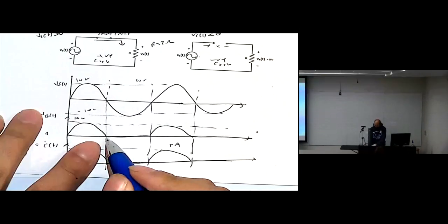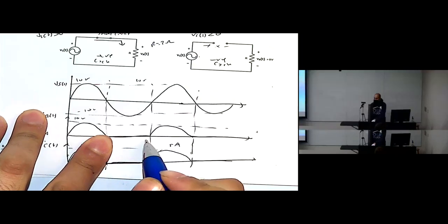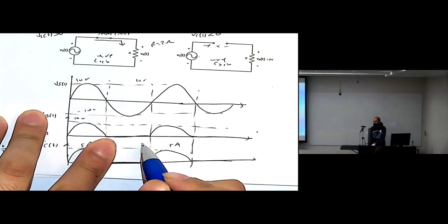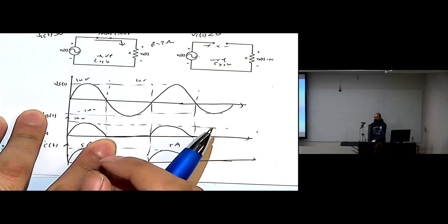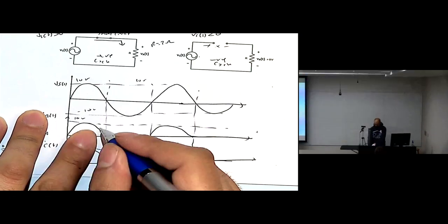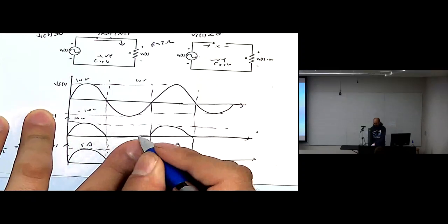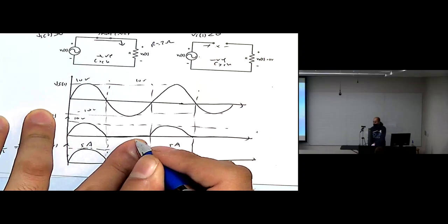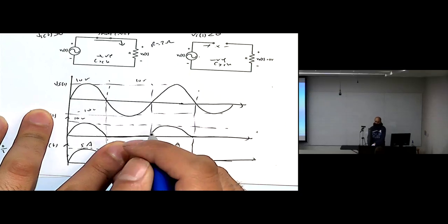This waveform we see here during the negative cycle, what's happening? It goes to zero directly. While if I add a capacitor, the capacitor will take time to reach zero. So it will discharge during this period instead of going to zero. That's why we are using the capacitor.